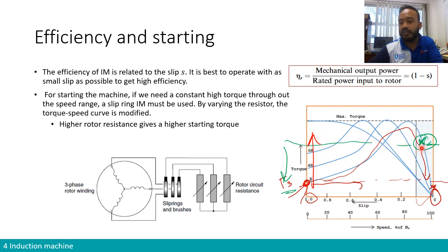So in this example over here, we have to increase the rotor resistance to a certain value where the starting torque is higher than the resistive load torque. And once it has started and goes to the synchronous speed, or reaches a very low slip, then you can reduce back the resistance of the rotor to this level so that the operating point will remain here.